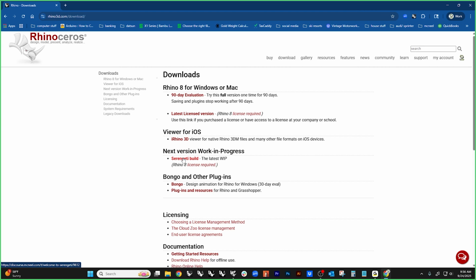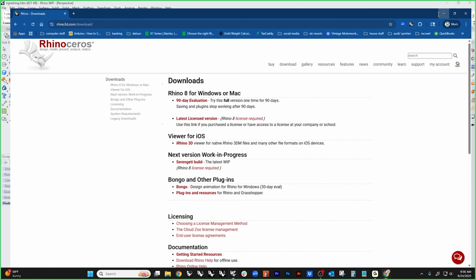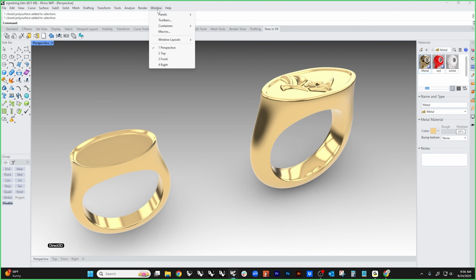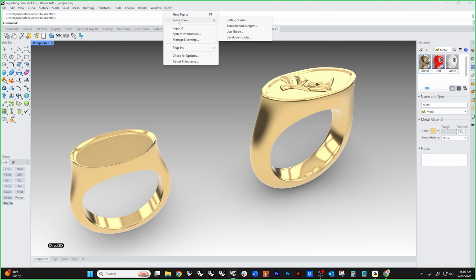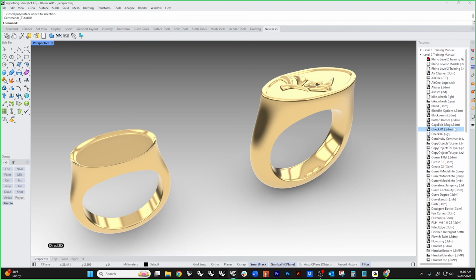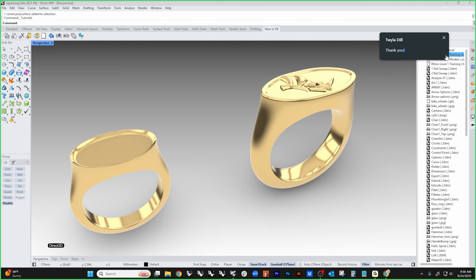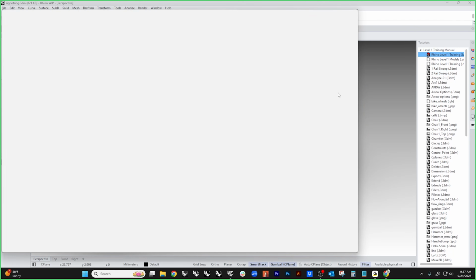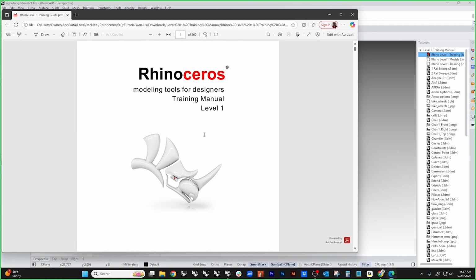Okay? Twyla says, this was interesting but didn't feel beginner. For someone starting with jewelry, do you have recommendations? Yes, I would recommend for everybody who is getting started to go to Help, Learn Rhino, Tutorials and Samples. It's built into Rhino. Do the level 1 training guide. Double click it. It's going to open a PDF. This is the level 1 training guide.